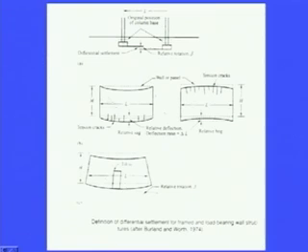Now, due to this there may be sagging of this wall, and there may be cracks which will appear on the wall panel. Similarly, there may be relative hogging like this, then tension cracks will get developed here on the top portion, and there may be relative rotation of this particular structure also. So, these are the definitions of the differential settlement, the rotation and the tilt.